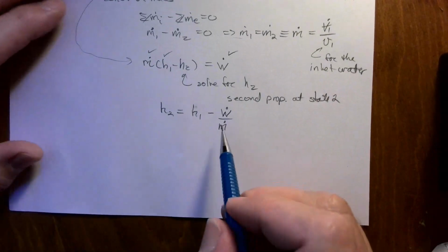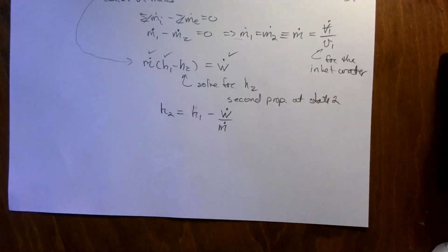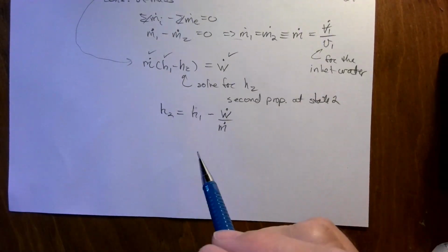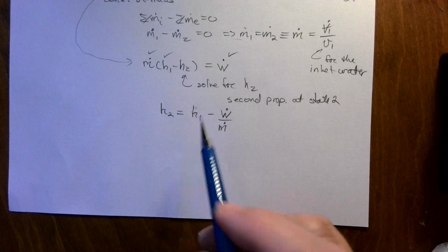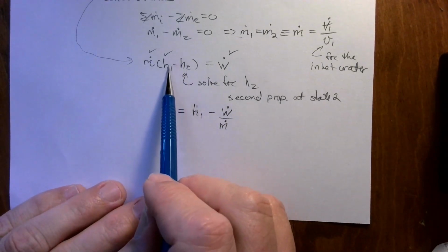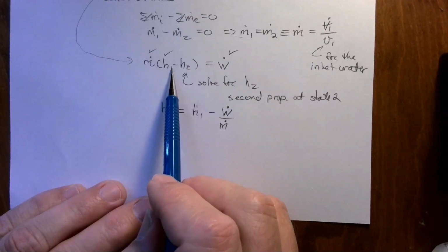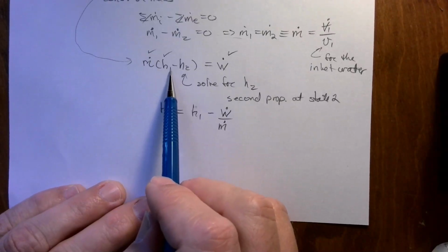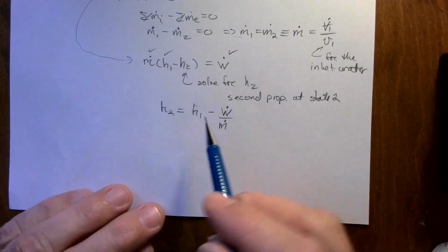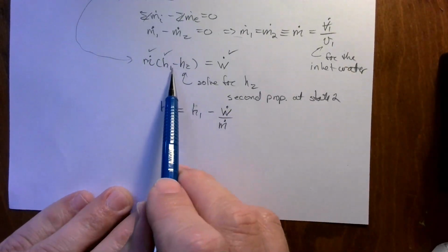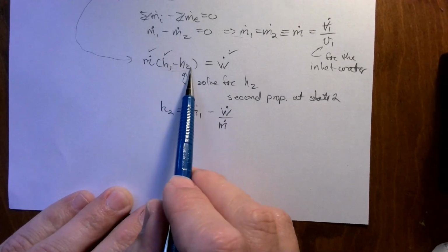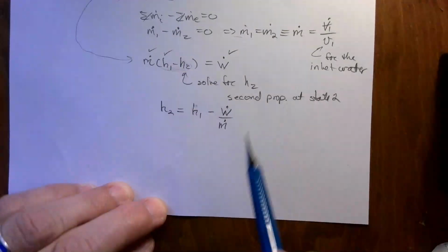Okay, so now we need to come up with H values. This is an incompressible substance since it's water, and both of those states are defined. They've asked us to evaluate, assuming incompressible, constant density and the specific heat given, assuming a constant specific heat. So instead of working it this way, we can go back and make an evaluation, express delta H in terms of temperature, and then solve this directly from temperature.